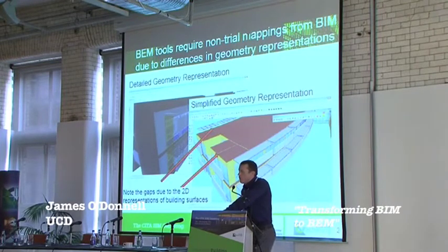And first and foremost, this results in what has been termed a thin wall model, and that is that the wall representations have no thickness. Thickness is only entered as a property. And we see here there are many gaps visually evident in this model. We also see here that there's a gap between the exterior facades and the shading. So walls are represented as planes, and heat transfer is perpendicular to the zone boundary. And this is important to take with us as we move on.